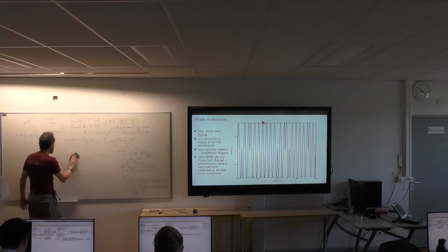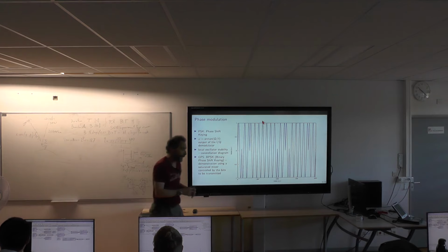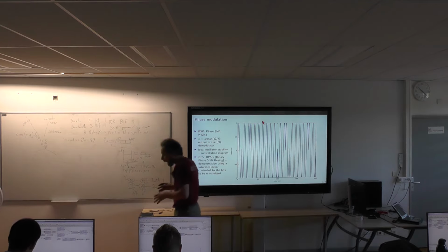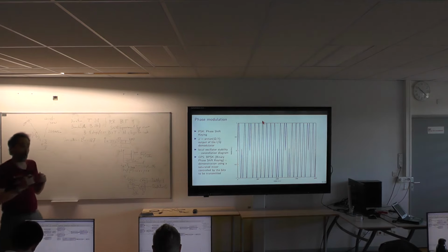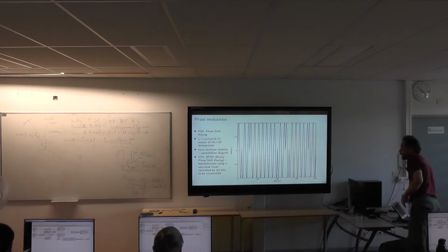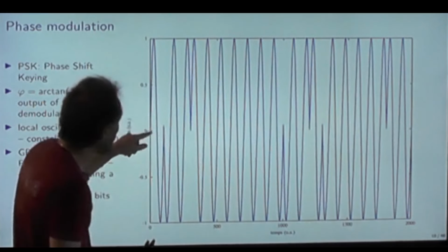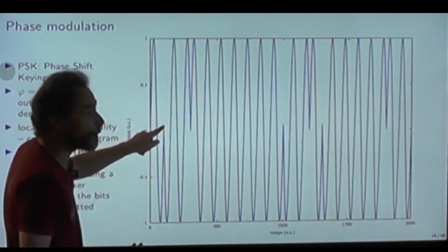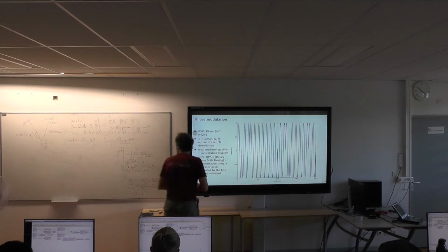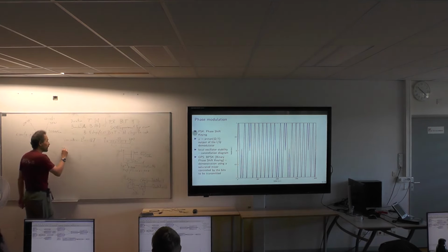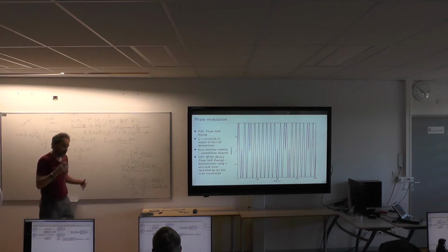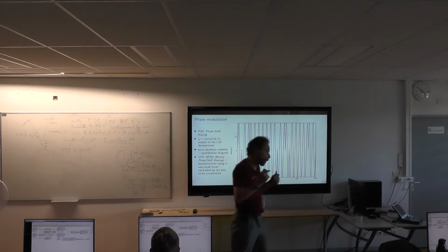So the last issue that we need to solve before we can actually decode a real GPS signal is the fact that all this information that we've been talking about so far is imprinted on the phase of a carrier. If you look here at this chart, you see what is binary phase shift keying. In BPSK, you have your sine wave, your carrier. This is a bit 0. Then you see that the phase flips. So now we have a bit 1, another bit 1, then the phase flips again. It's a 0 again. So in binary phase shift keying, BPSK, the phase can have two possible values, 0 or pi, 0 encoding bit state 0, pi encoding bit state 1, for example.